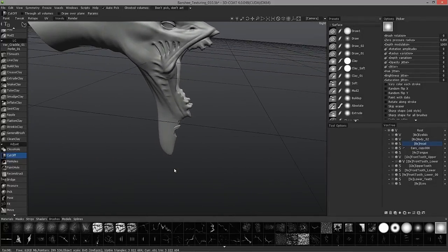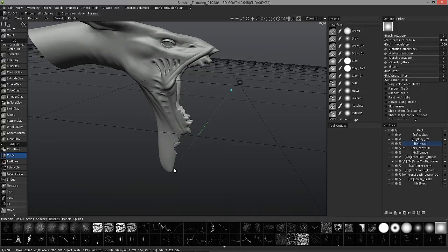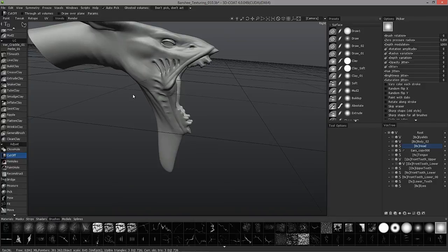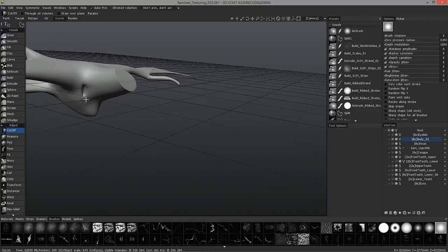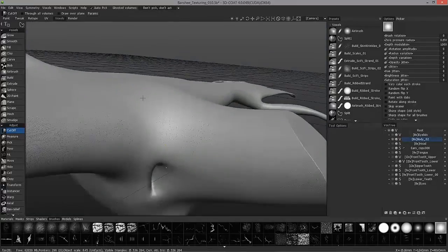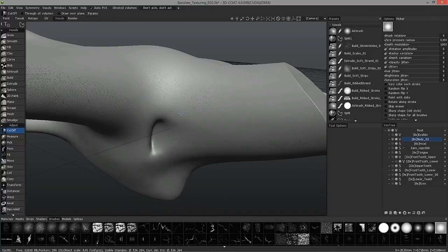All right. So I'll undo a few times here. Okay. So again, with voxels, you are turning on and turning off volumetric pixels in 3D space. It's literally like digital clay. And what happens is you, the viewer, will never see the voxels yourself. It's an internal calculation just for the application. But what you do see is that external mesh that conforms to whatever changes you make to that volume, and it tries to maintain an even distribution. So that is kind of counterintuitive to try and switch from an area that you've worked to apply localized tessellation or localized subdivision and then go back to a mode that's going to simply even everything back out.